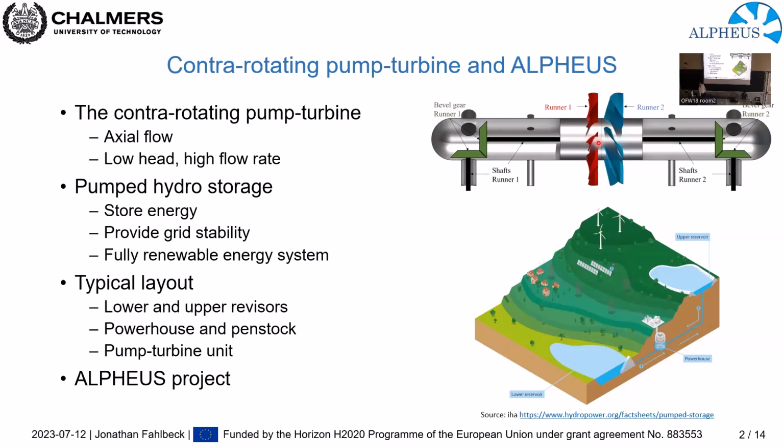So a typical layout is we have an upper and lower reservoir, and in times when there is a high energy surplus, we can pump water from the lower reservoir, and then we can release water from the upper reservoir when there is a higher demand from the electrical grid. A problem with pumped hydro storage is that it's traditionally developed for high head situations, meaning that there is a large height difference between these two reservoirs.